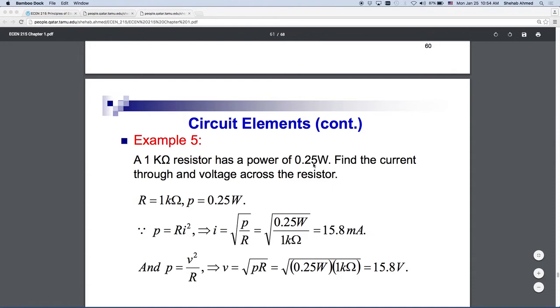Your adapter power supply is very different from the value of the resistance used in a large power drive circuit. It's a very different power dissipation value, but the resistance is the same. So it's the same 1 ohm resistance here, 1 ohm resistance here, 1 ohm resistance here. However, it's rated for different power levels. And so when you go and buy resistors, you have to buy them for a certain power rating. Quarter watt, half watt, 1 watt, 5 watts.